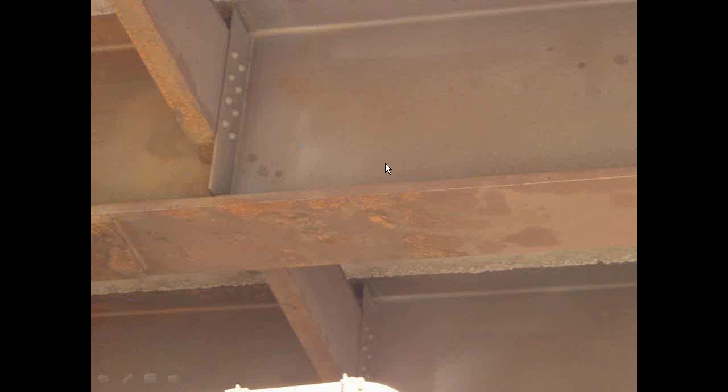There's one there, the same thing. This was all abrasive blasted. You can see how it's rusting back heavier down here, on the bottom side. Yeah, there's a little bit of rust up here on the vertical. There's probably a little bit of contamination there, but not near as heavy as it is down here. But the underside of the bottom flange is where the salt contamination is always the worst.